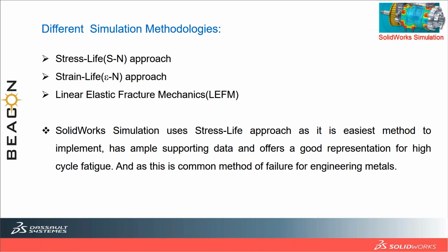When you check for more than 10,000 cycles and above, you find almost the same results whether you do physical testing or SolidWorks simulation. You will find the same values there. And this is a common method which is used for all engineering metals.